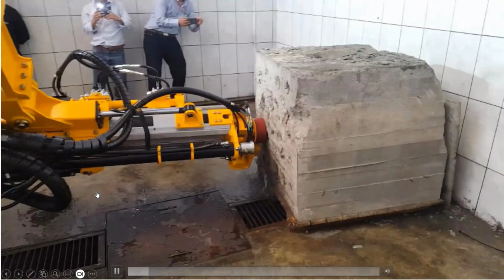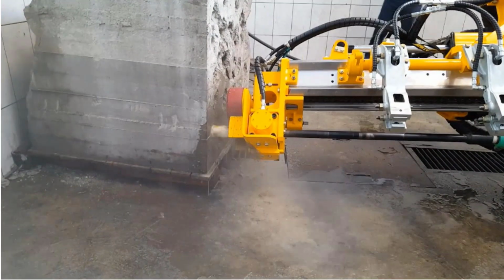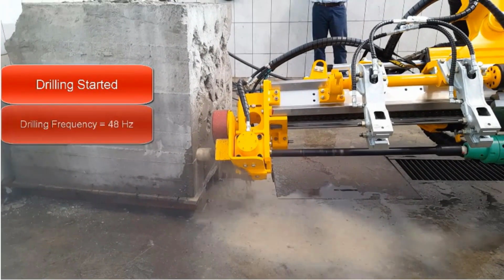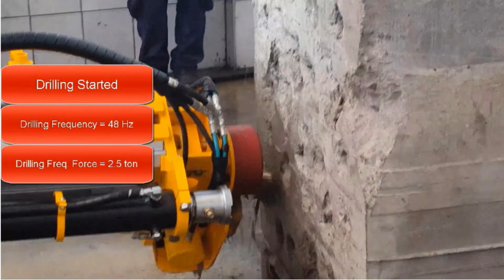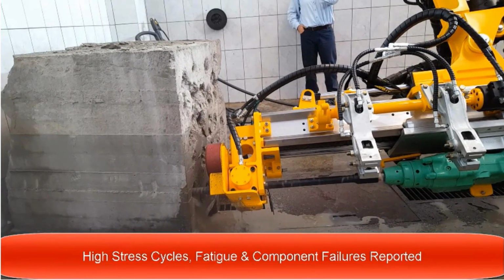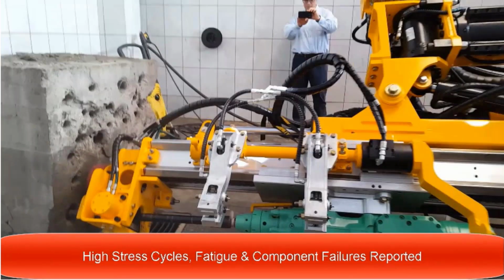This is the actual RESEMIN boom assembly with a drill machine. You can see how the drilling has started. During the drilling process, there is of course a lot of vibration that gets back to the machine from the source, and of course that causes fatigue, probably not suddenly, but after certain years. Due to the cyclic loading, field failures are happening a lot.